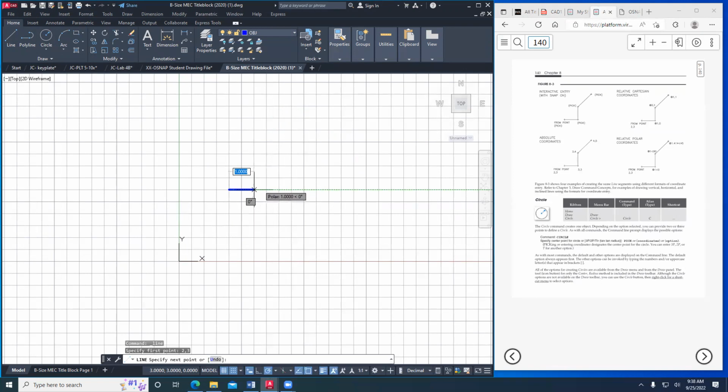It's right there. But if I were to use the old school way, I'd say @1, less than symbol, 0. And then again, it's so much easier to use polar tracking to go up 1 and 90 degrees, but again, old school @1, less than symbol, 90. And then to get this other one at 45 degrees, or at least at 1.414 angle 45, if I can just get this out to a 45-degree angle, I could type 1.41.